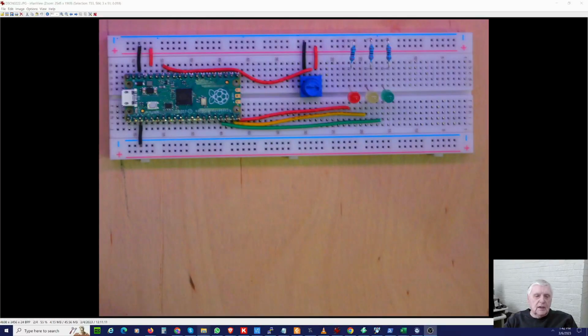The homework for Lesson 6 on Raspberry Pi Pico, provided by Paul McWhorter, covers devices that he covered in previous lessons. In this lesson, we will be using LEDs and a variable resistor called a potentiometer. Here in this shot, we can see we have 3 LEDs installed: the red, yellow, and green. Each one is attached on the positive side to the GPIO pins 15, 14, and 13 respectively.